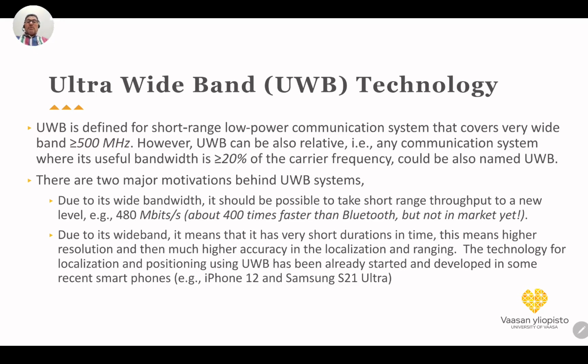However, due to disagreement between some companies, they didn't come to one solution, or at least a compatible solution, to support the physical layer. Some companies want to use the multi-band of ultra wideband, which is based on OFDM modulation, and others want to use direct sequence ultra wideband, also called radio impulses or the impulsive solution, and those two solutions were not compatible. So the standard was not successful, it failed.